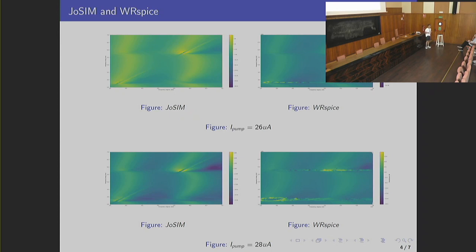A parametric amplifier works in such a way that it always has a regime where it amplifies best. Let's say if we put too much power into our system, the current in the junction will be very close to the critical current, and that will give us a bifurcation regime where we have 2 solutions at 1 point. That is why in that regime we will have some crazy behavior which decreases our gain. On the other side, if you put in lower power, our nonlinearity will not be so big, and amplification will be lower.